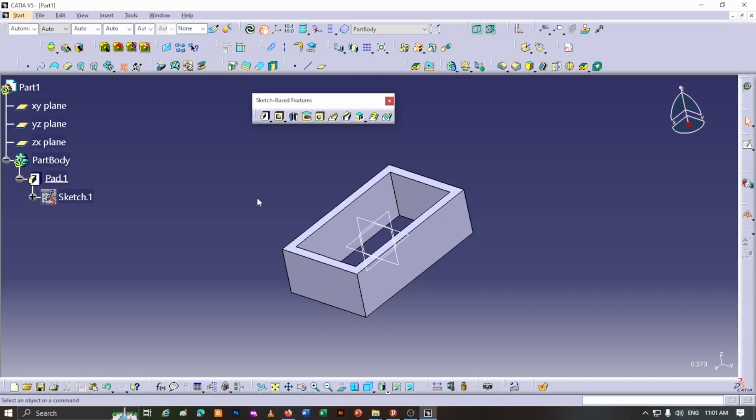To use this tool, we need a sketch as well as a solid body. The sketch determines which design will be used for the removal. Assume we now have a square box with a wall thickness of 15 mm. We want to open a window on one side of it. The shape of the window is a circle. The circle has specific dimensions and location.